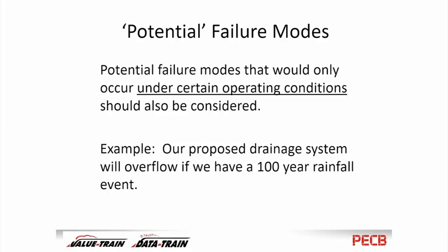Now there's a lot of water coming into this dike system, so it has to hold that too. But every so often, every 100 years, and our Weather Bureau calculates 100-year rainfall for every part of our country, what if that happens? Do we have to design the wall to hold 100-year rainfall plus the tank failing?